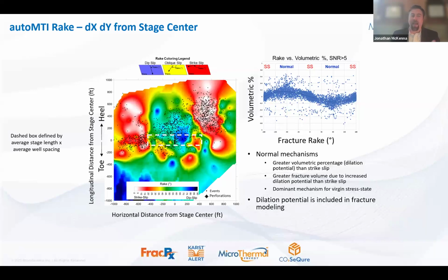We even have another workflow where we can see a lot of events occur very quickly right when you start injecting, and that's showing a lot of times where the fracture's collapsing on itself, where you have these open fractures due to proppant that may be shifting and closing very quickly due to actual depletion, and they coincide with how we've done modeling of the proppant as well. So that's one example of how we've done that testing.